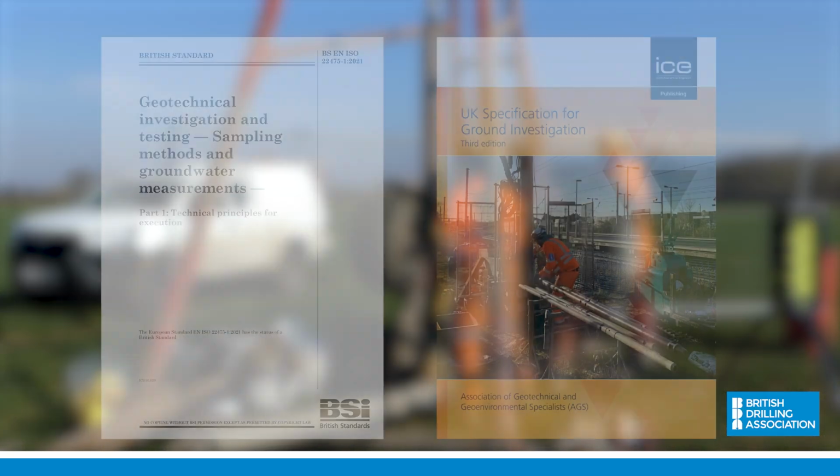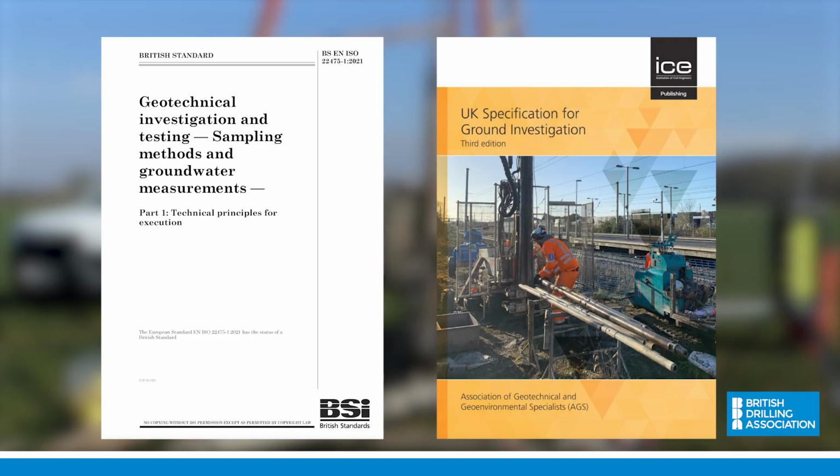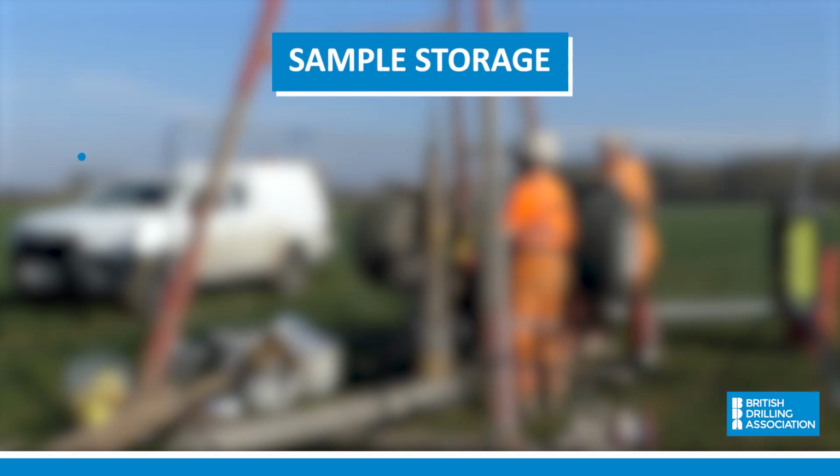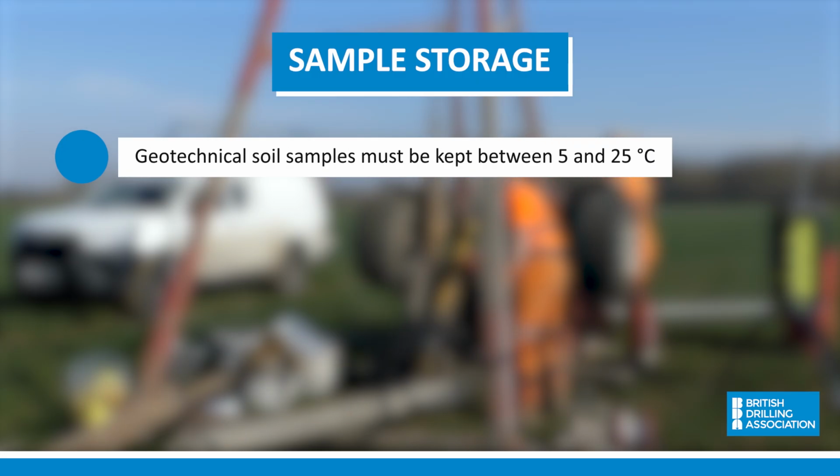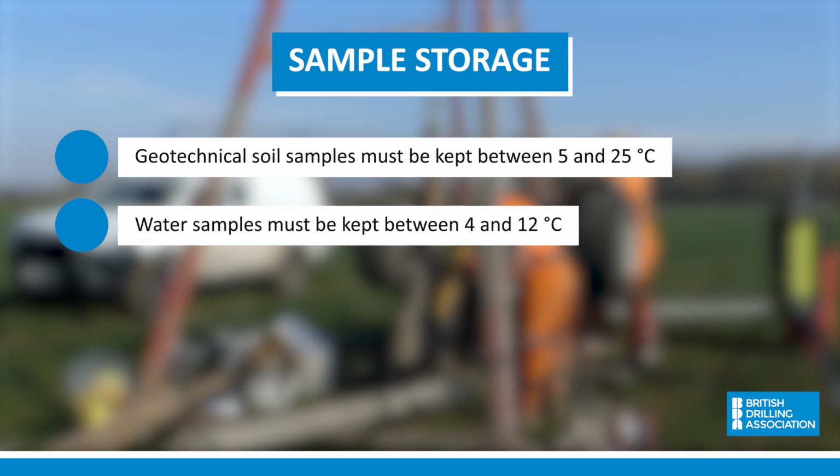BS EN ISO 22475 Part 1 and the UK Specification for Ground Investigations require these storage and transportation conditions to be between 5 and 25 degrees Celsius for geotechnical soil samples and between 4 and 12 degrees Celsius for water samples.